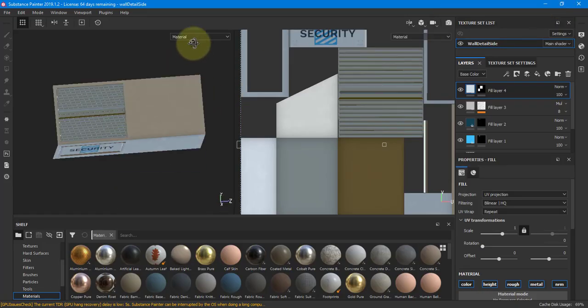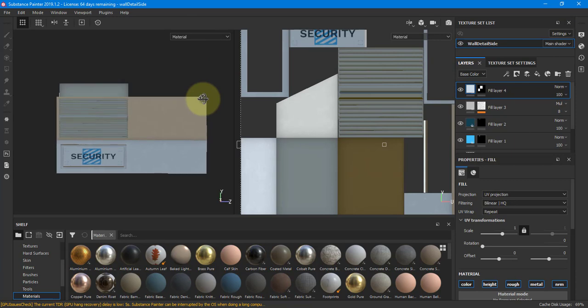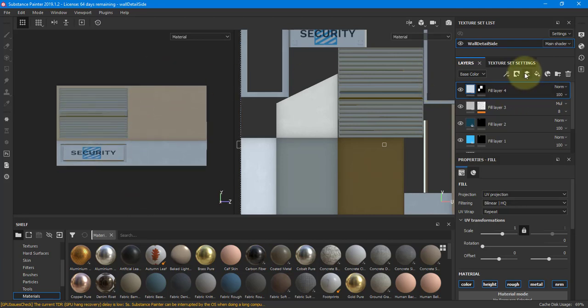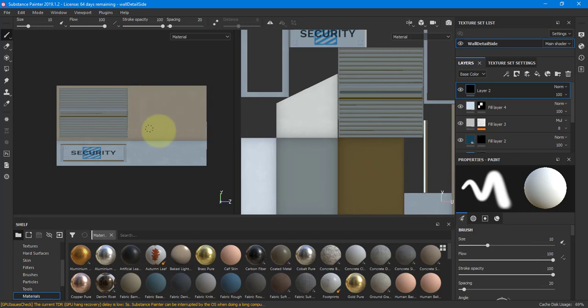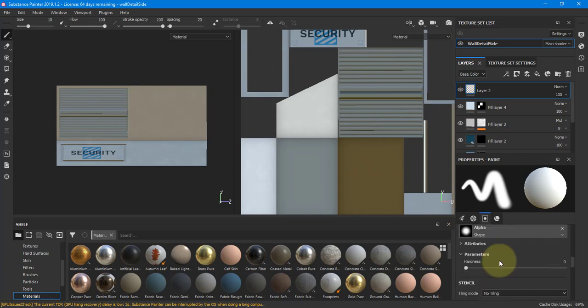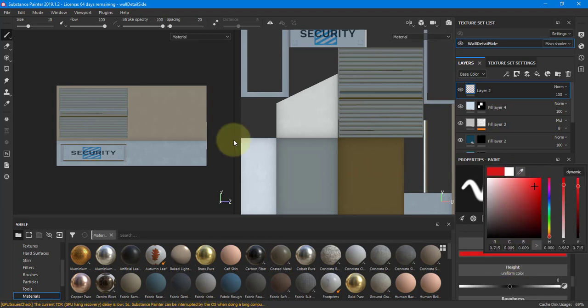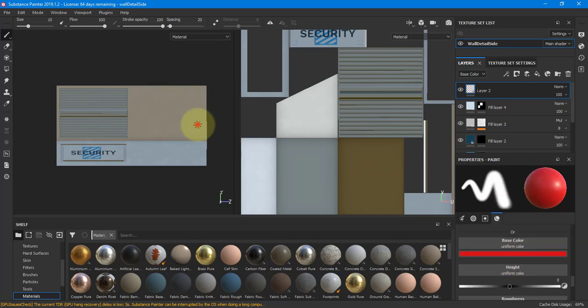All right, this is Substance Painter. Again, it's a free one. We need to be able to get into this. This is where we're going to be doing our texturing at. Up until this point, all the texturing we've done has been just like flat materials. So metals, plastics, glass, that kind of thing, more architectural based. In this one, we can actually go through and actually paint onto surfaces exactly where we want stuff to happen. So for this object here, I can make a layer, and I can go with my brush. I did that last class too. Pick a different color. And I can paint right on top of that. Okay, and that's what we want to do.